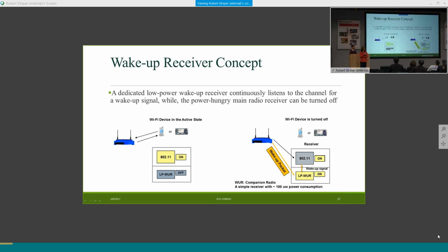But there is one thing, and it's coexistence. If you have Wi-Fi, you benefit a lot from coexistence compared to Bluetooth and Wi-Fi, because a lot of effort goes into in-device coexistence mechanisms between them. For example, if Bluetooth is receiving, Wi-Fi doesn't transmit. These are handled in the device, or through the frequency hopping of Bluetooth. There are mechanisms for coexistence, but none of them are systematic from a network point of view. So if you have it all in Wi-Fi, it's good.